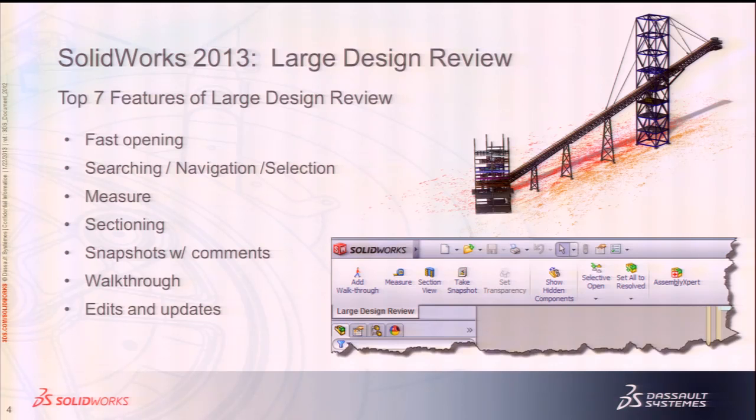When you're sitting with that client, you're going to want to be able to measure, and you're able to do that in large design review. Figure out how big is this thing we're speaking about. How big is this design we're showing? We can measure. We can section, again, using all the same tools and interface that you're used to using in SolidWorks when you're designing. You can use them in this very, very lightweight mode to find your way through and explain the design.